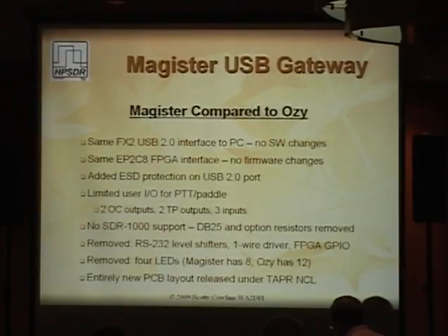So here's a comparison to Aussie. No software changes on the FX2, no firmware changes on the FPGA. Again, the added ESD protection. We have 2 open collector outputs, 2 totem pole outputs, and 3 inputs to hook to your paddle or your PTT. No SDR 1000 support. We took the DB25 off, and there was a bunch of drivers and resistors and a huge bunch of manufacturing option resistors. We removed all those.